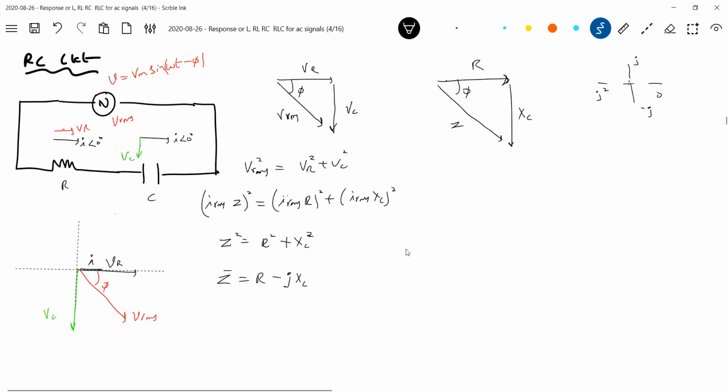At least now, after getting this much idea, please think in a different way. The complex numbers you studied, the physical interpretation should be according to the requirement. That is why complex numbers were brought in. This is about the voltage triangle. This is about the impedance triangle. And then I want the phase angle of the circuit. Tan phi should be equal to XC by R. What is XC? 1 by omega C. This is R. So by varying frequency, I can control the phase angle.